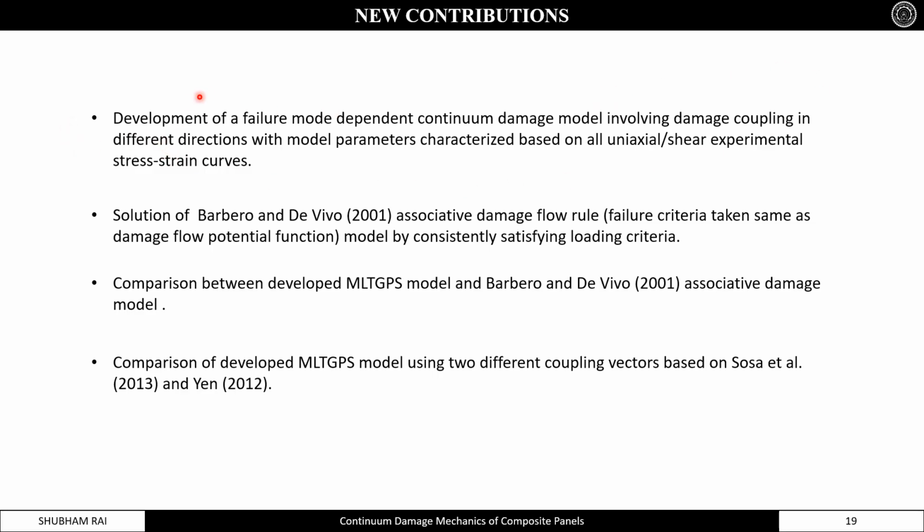Now these are the new contributions that have been made. Firstly, we have developed a failure mode dependent continuum damage model characterized based on experimental test curves. Second, we have solved the Barber-Vivo associative damage flow rule model by consistently satisfying loading criteria, and we have compared the developed model with the Barber-Vivo model, and it is concluded that the developed model is predicting damage variable values consistent with the strength properties. Third, we have compared the damage prediction capability of the developed model using two different coupling vectors.